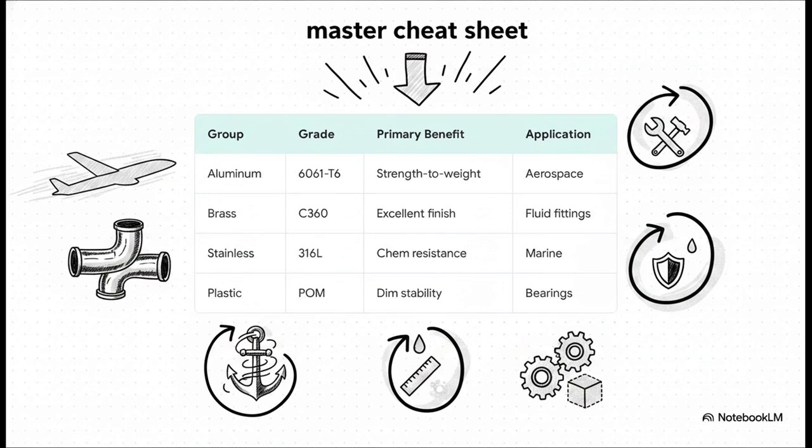You've got your non-ferrous metals like aluminum 6061 and brass C360, which are prized for their strength-to-weight ratios and those incredibly fast, beautiful finishes. Then you have your ferrous, iron-based heavy hitters, think stainless 316L, known for extreme chemical resistance. And finally, engineering plastics like POM, which bring their own distinct solutions, like dimensional stability, to the table.